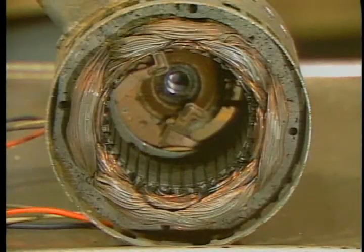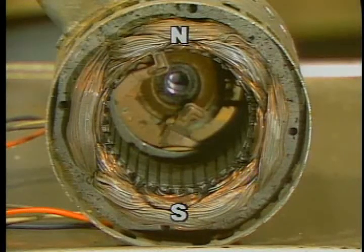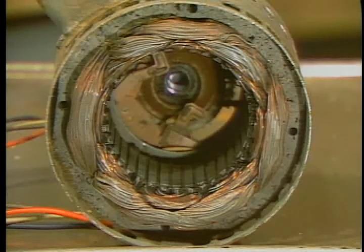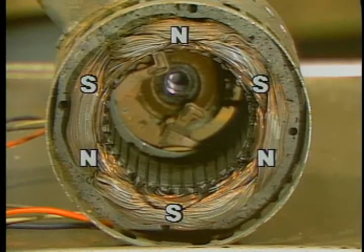An AC motor which can run at more than one fixed speed makes use of this principle. When you set it to run on a different speed, the switch connects the individual windings in the motor for a different number of poles. For maximum speed, the motor is connected for the fewest number of poles. Reconnecting the windings for twice as many poles cuts the speed in half. 3 times as many poles produce 1/3 the speed, and so on.